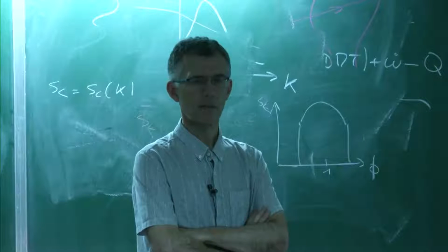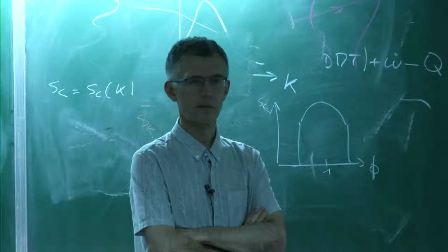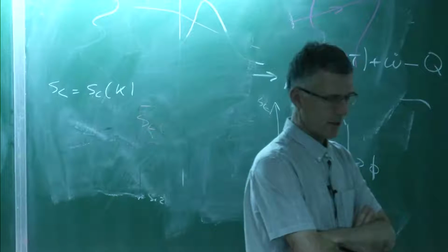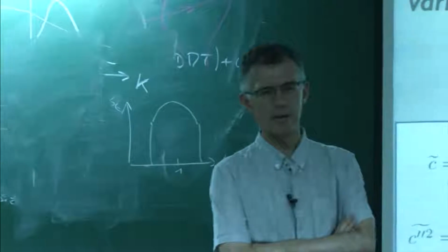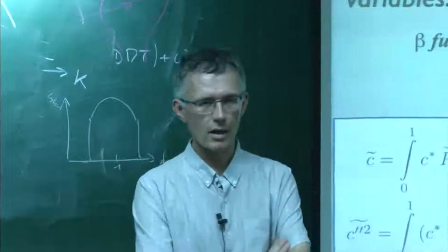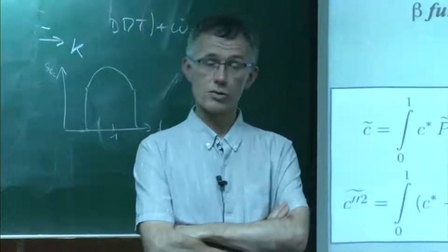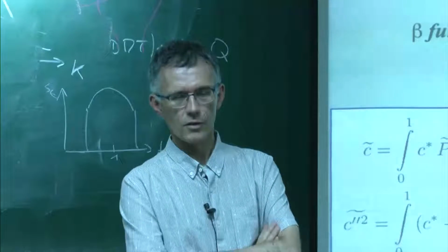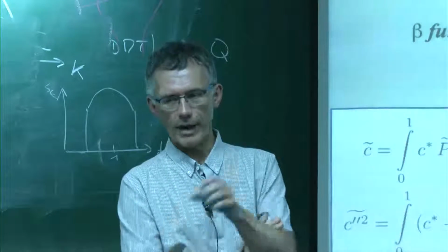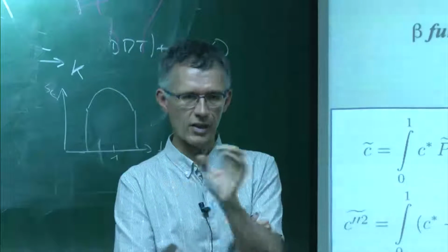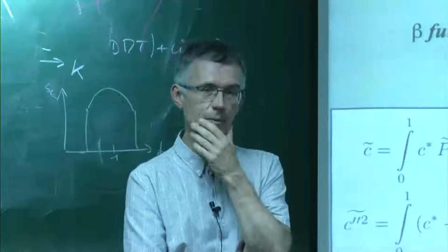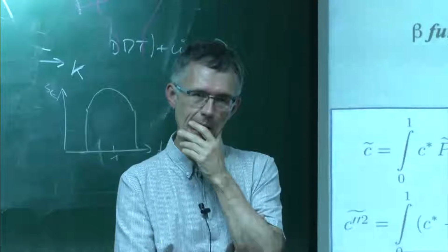Does the EDC model take care of the finite chemistry? Well, EDC is one name, but there are many implementations of EDC. So you have to look at the implementations you have. Normally in EDC, you have some kinetics somewhere. It's a combined expression with kinetics and some eddy breakup formulation. So there is some kinetics there, yeah. So if there is kinetics, can it not take care of